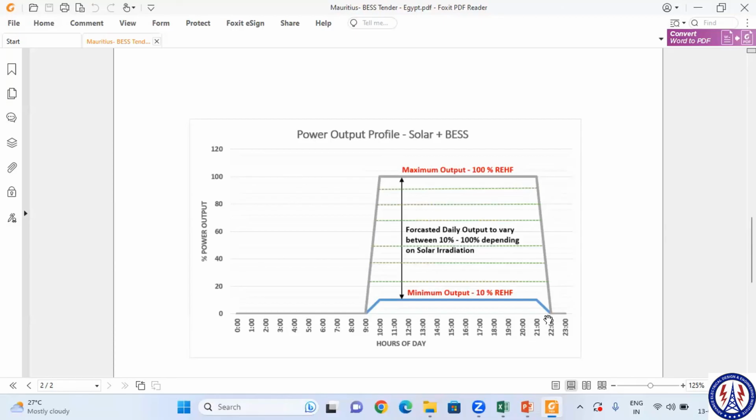But the point is, on the AC side you can serve a load of only close to 4.5 megawatt. Because if you operate for 5 hours at a load of, let's say, 5 megawatt, how much energy are you going to release? 5 megawatt into 5 hours, 25 megawatt hour, correct? Okay. So 25,000 kilowatt hour of storage you require. So you need 25 megawatt hour storage only.